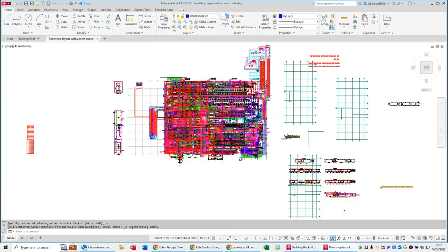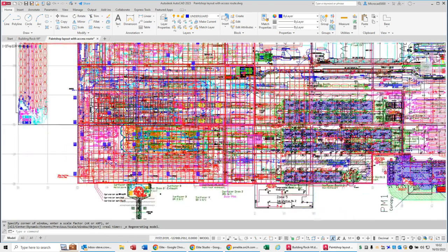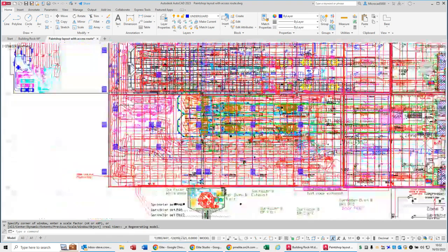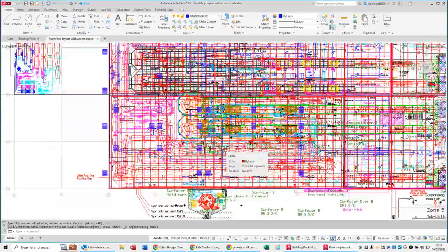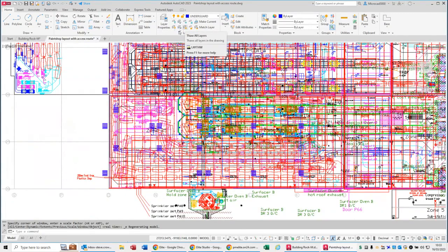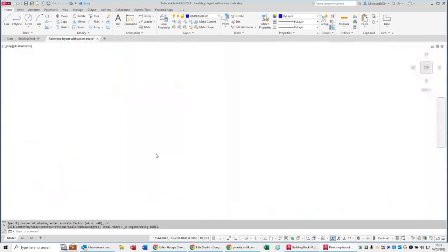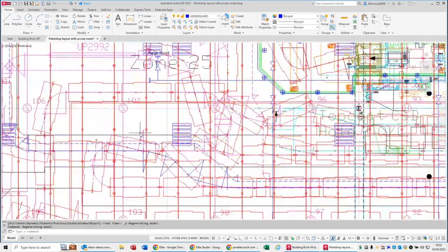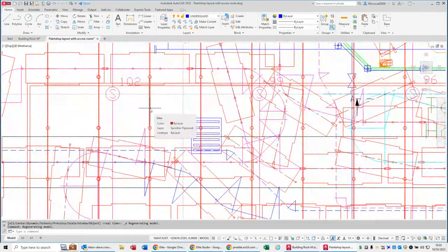But look at the layers in this drawing file. Masses and masses of layers. Okay. So let's have a look at one of these other buttons on the ribbon panel there. And it's this layer isolate and unisolate. So what does this do? Well, in this particular drawing file, these vertical red lines are a sprinkler line. And I'm the guy having to lay out some more sprinklers. Okay, so I need to start turning layers on and off.